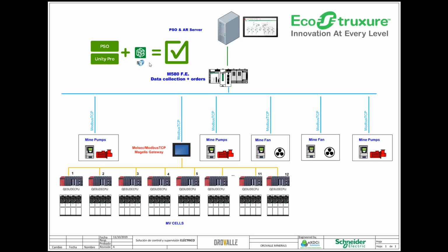In order to implement this solution, we always use a tool called SG2, and this tool permits us to define the type of different devices, and gives us the possibility to automatically create all the tags that are coming from these devices. And if we have defined some genies in the SCADA, automatically all the information for the SCADA is generated thanks to this tool. So for us, this is an important tool in order to do a quick project and to have the standardization of the project. So I will show you this.